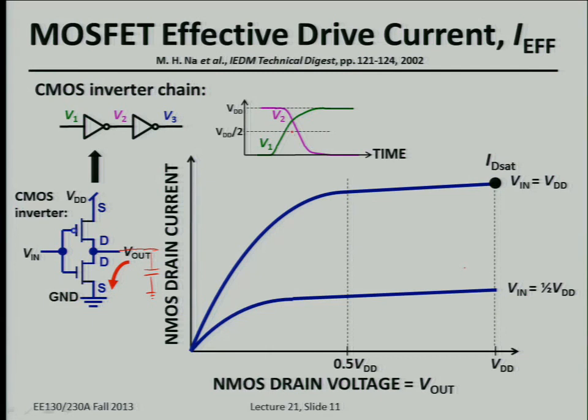One thing that the industry likes to keep track of is the propagation delay, that's tau sub P. How long does it take for any change in the input to propagate to the output voltage? Usually we measure it from the 50% point. When the input voltage changes to halfway up to VDD, how long is the delay until the output drops halfway down? That's the propagation delay for the high to low transition.